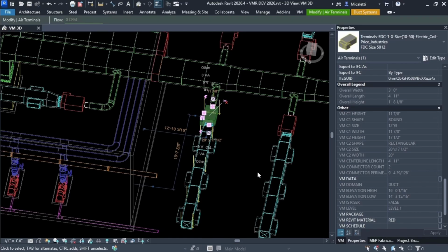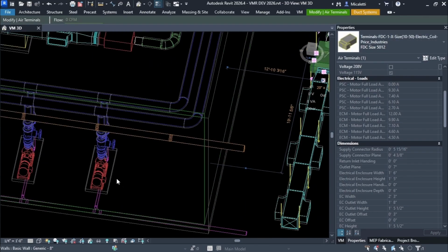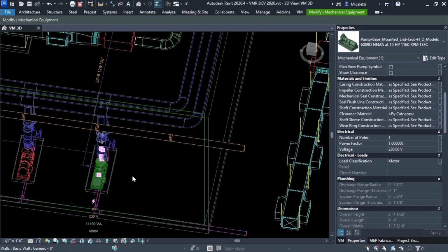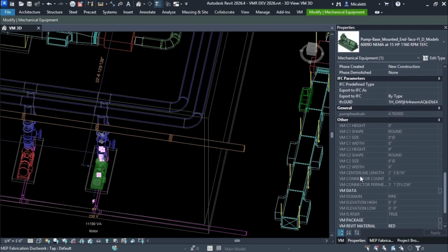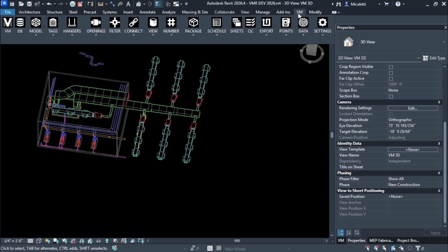Parameter name, there's an underlying GUID, right? So the height parameter is not the same height parameter throughout Revit, and they have to do this because Price needs a parameter called height, and Taco may need a parameter called height, and these two manufacturers are not coordinating with each other and using the same GUID. So you have two parameters named height, but they're not the same. In this way, VM kind of unifies all of that data for you.